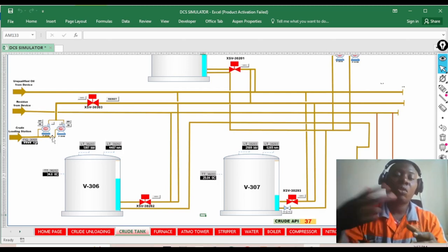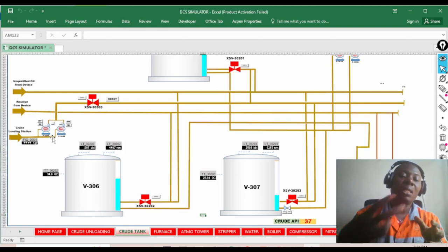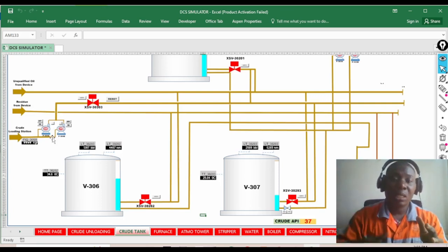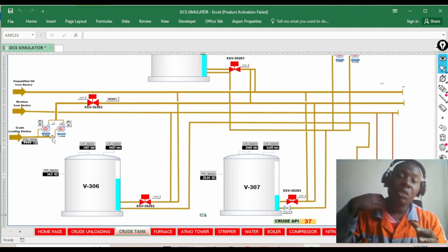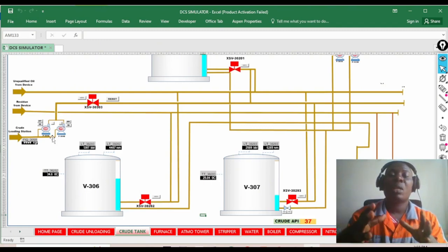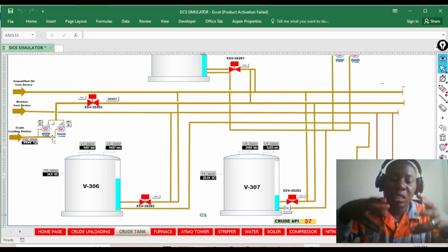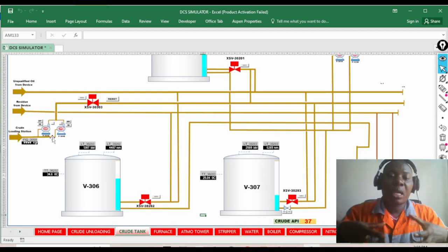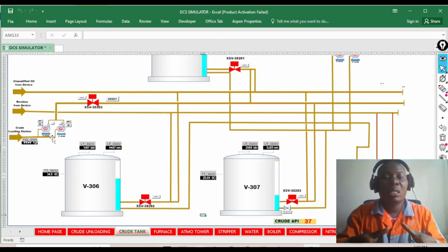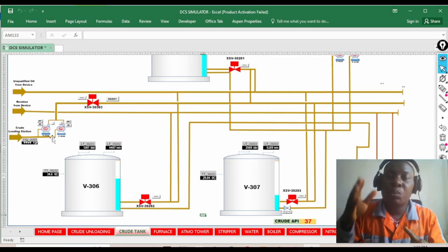Now the continuous running of the pump is going to make the seal inside the pump become very hot. When it is continuously running, it will damage the seal and might even cause an explosion. Okay, so in this case, what we are trying to safeguard is the pump. We are trying to safeguard the mechanical integrity of the pump. So this is what they call an asset protection.